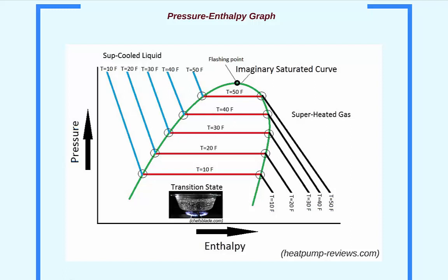Though this particular plot is not for water, we have previously talked about how, at 14.7 psi, the saturation temperature of water is 212 degrees Fahrenheit. This chart depicts that temperature remains constant inside the saturation dome, and what that temperature is depends on the pressure the mixture is operating at. Notice that inside the liquid-vapor region, changes in enthalpy occur at a constant temperature.